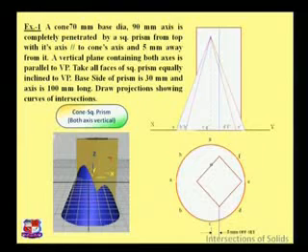Now find out points of intersection between these two solids. One point is here. If I draw a vertical line from here, this is the point of intersection on OG, on OH, on OA, on OB, OC, OD, OE and OF. So these are the points of intersection between the imaginary generators drawn over the cone and the square of the square prism.